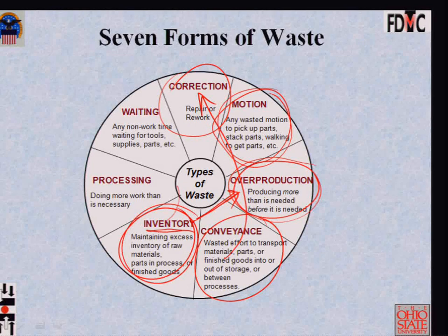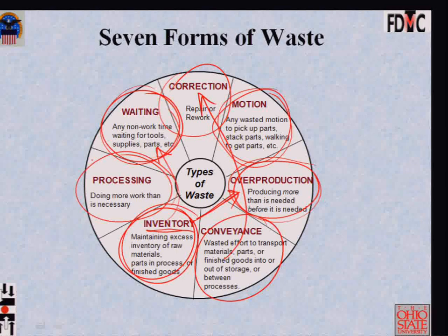And of course, the work in process waste often relates to the waiting waste. Any time that orders wait in queue because the machine's broken down or there are other orders in front of it, it costs. It's basically the carrying cost of inventory. So queuing waste, waiting waste is the sixth form of waste. And of course, a very subtle but often forgotten waste is processing. See, we industrial engineers, we tend to break up any work process into some classical elements. The elements would be operation, transport, inspection, waiting, and then delay of any form.